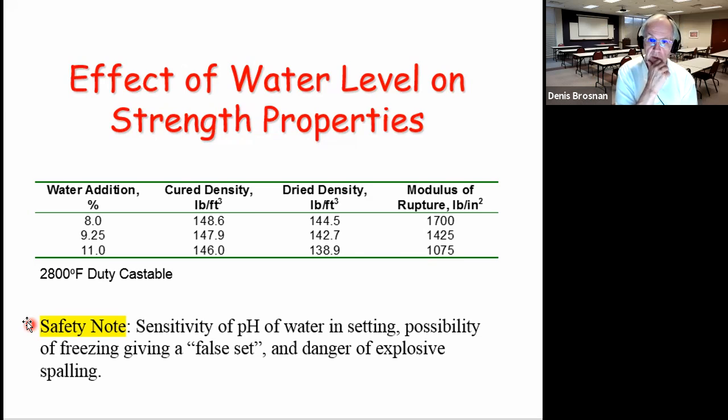And so when you begin drying out the furnace, preheating the furnace to dry out that castable, which is always recommended, that castable can experience explosive spalling, steam spallation. You remember that from the drying course. So occasionally someone is killed by this in a large industrial furnace.